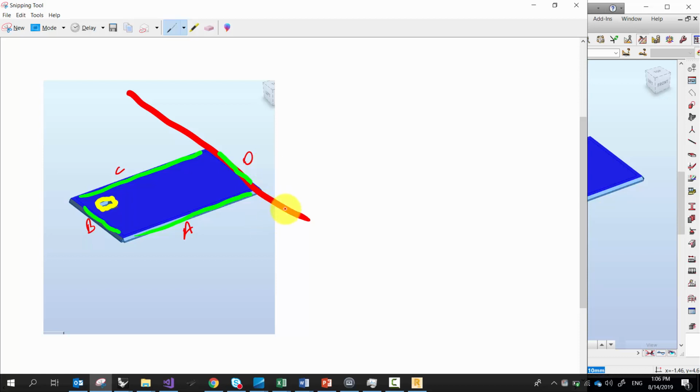So now the question is how are we going to make that association between bar 1 here, which is the mullion, we're calling it mullion right now, data-wise it's a line, and D, which is the edge of a panel, which currently, before it's actually a panel, is a line or a part of a polyline, right?